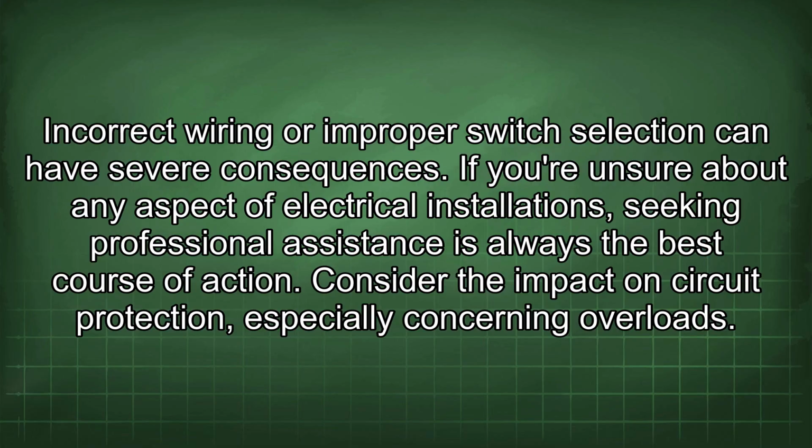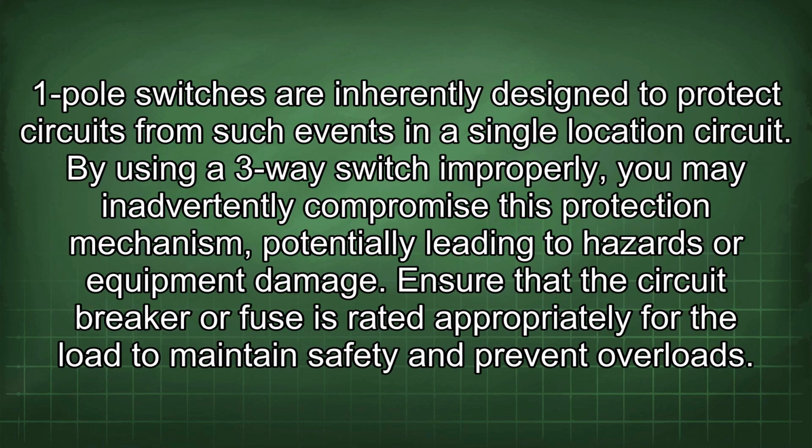Consider the impact on circuit protection, especially concerning overloads. One-pole switches are inherently designed to protect circuits from such events in a single location circuit. By using a three-way switch improperly, you may inadvertently compromise this protection mechanism, potentially leading to hazards or equipment damage. Ensure that the circuit breaker or fuse is rated appropriately for the load to maintain safety and prevent overloads.